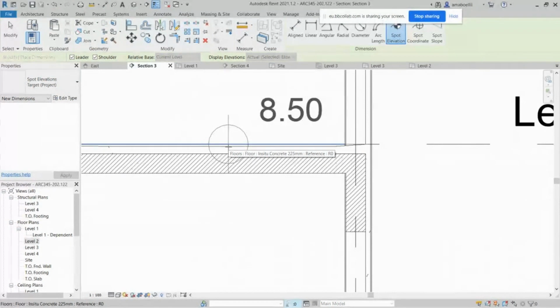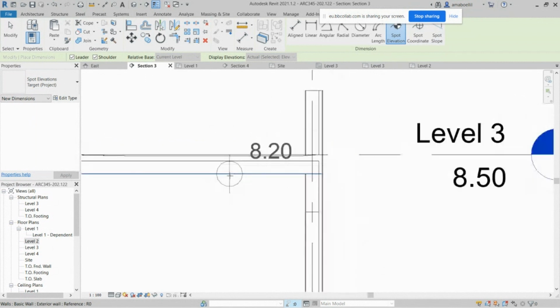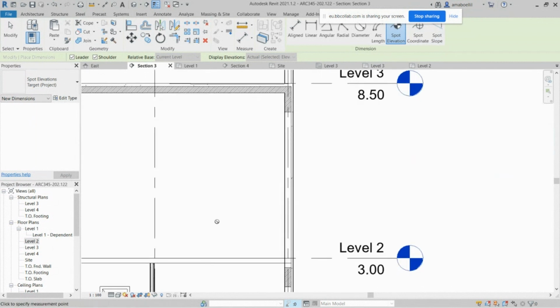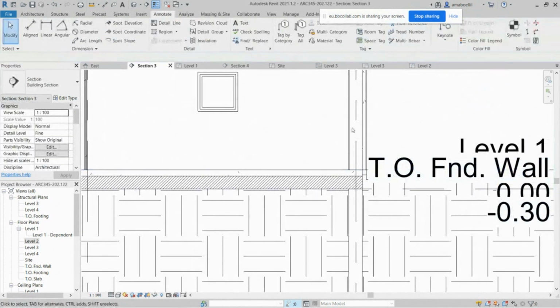If I say 8.5 mistakenly, the contractor would say that the roof is level, but it's not. So it's better to refer to here or the bottom of the slab, and then the contractor will do the math and find what the other things in here are. I actually prefer to use the top of the slab as the upper level, and that can be done, by the way. Instead of taking the slab like this at the level of level 1, for instance, you make the slab starting from level 1 and the finishes flying from level 1, so that you draw your level, and above it you put the finishes, below it you put the slab. So the level is referring to the top of the structural element, not the top of the finishes.